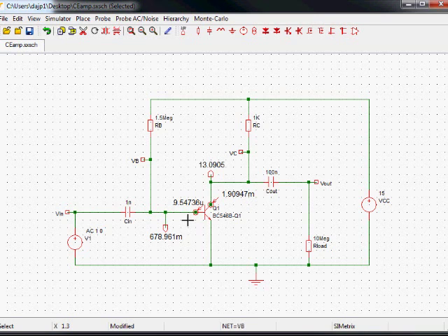By taking the measurements of VBE, the voltage between the base and the emitter, and IC and IB, which you can work out from VC and VB for your particular transistor, you should be able to work out the values of IS and BF that you need to use in the transistor model to reflect the characteristics of the transistor that you're using.